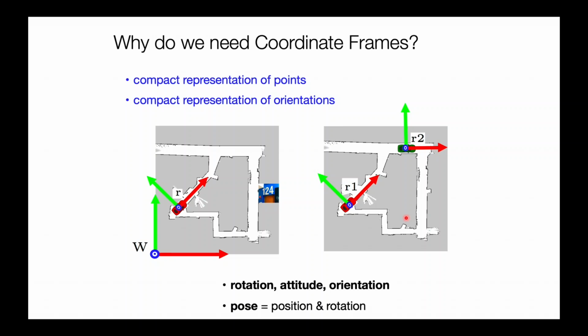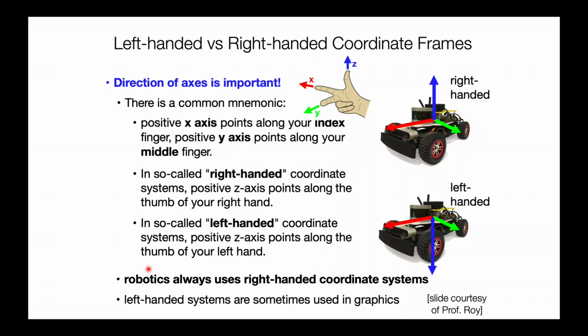So you have X, Y, Z, and theta, which fully describes where one robot is located, either with respect to another robot, in which case you are talking about the frame of reference on the robots themselves, or their absolute position and pose with respect to the world frame or the coordinate axis on the bottom left. Right, so this makes talking about the pose of the robot very easy and straightforward, and that's why every robot requires some coordinate frames to describe its position.